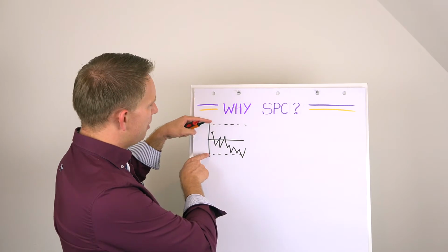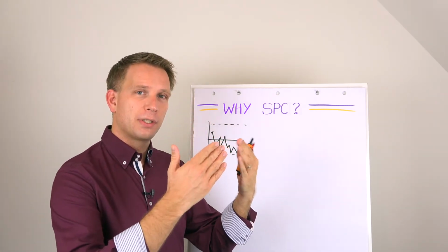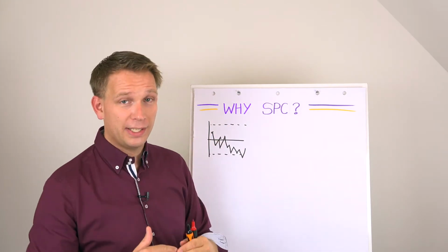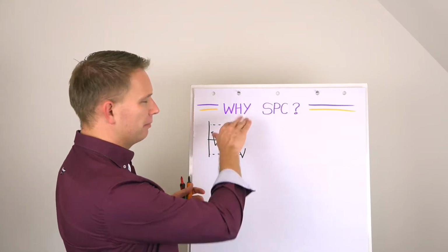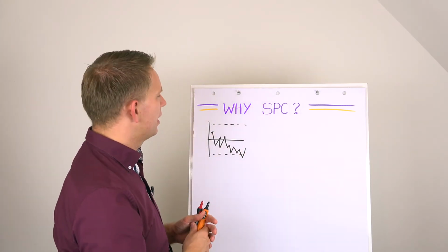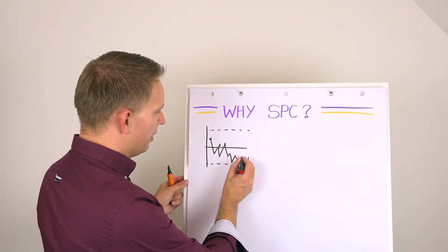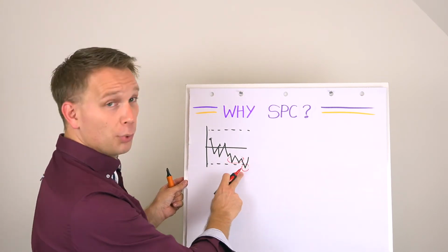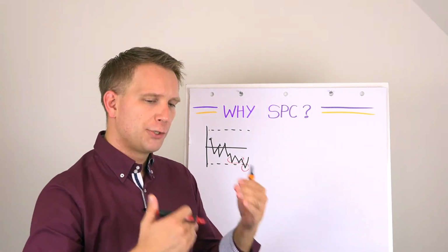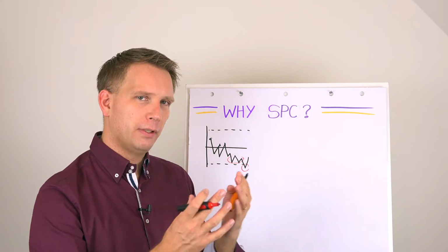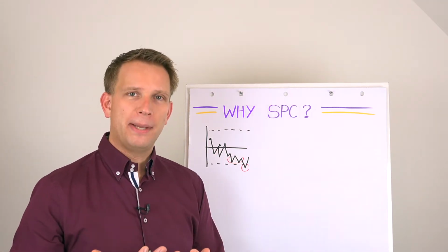These lines, the upper and lower control limit, are 3 standard deviations higher than the average and 3 standard deviations lower than the average. And then when we go and check, there are some middle lines on 1 and 2 standard deviations as well. But at some point we see, hey, something is going wrong here. This point by itself would also indicate something went wrong, but here already we see there are too many points outside of our secondary control limits. But what does that mean?